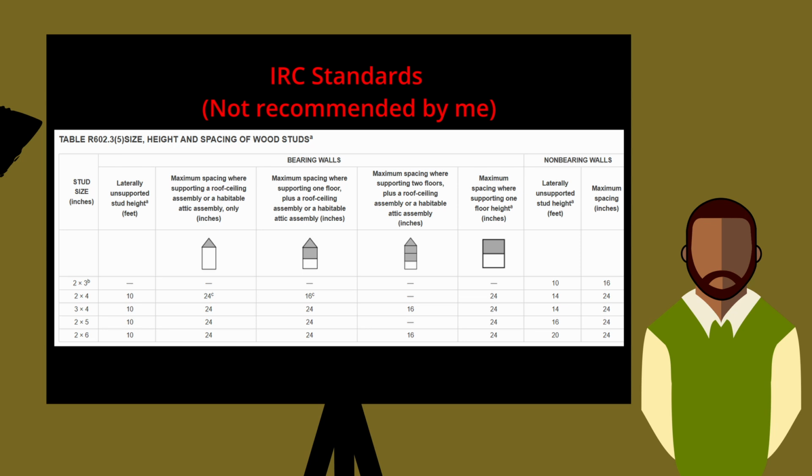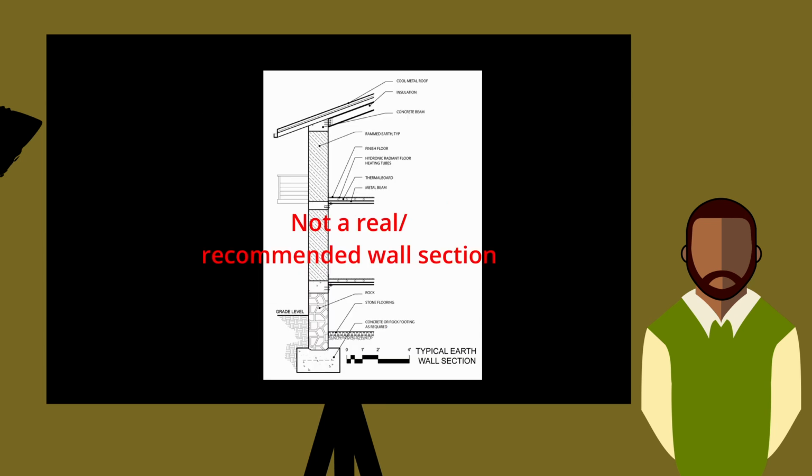And in terms of the walls, 2x4 versus 2x6 conventional framing, these things are going to differ based on the ceiling height, right? I think the IRC says that if it's over 11 feet or something, then you can use a 2x6.